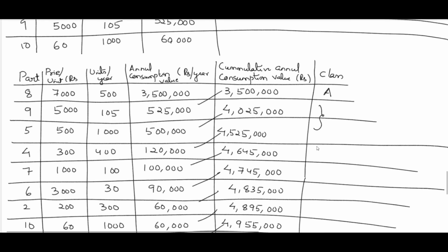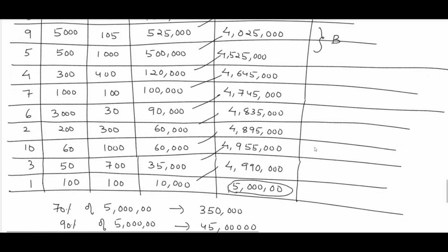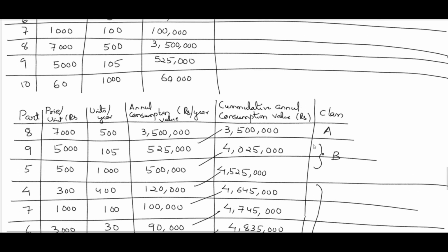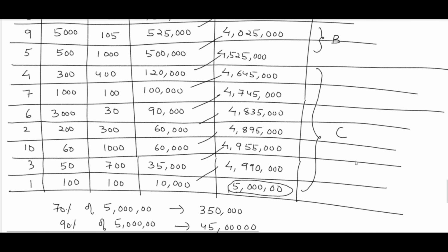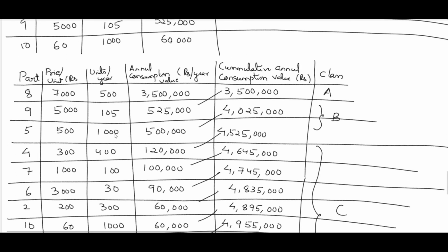It is much closer. Whereas if you consider the fourth part also, it is 46 lakh something, which is much more. And if you consider only the ninth part, it is 5 lakh less. So an excess of 25,000 is better. That's why we write down that it belongs to category B, that means the ninth component and the fifth component. All the remaining belong to category C, which comprises 10% of the total cost.